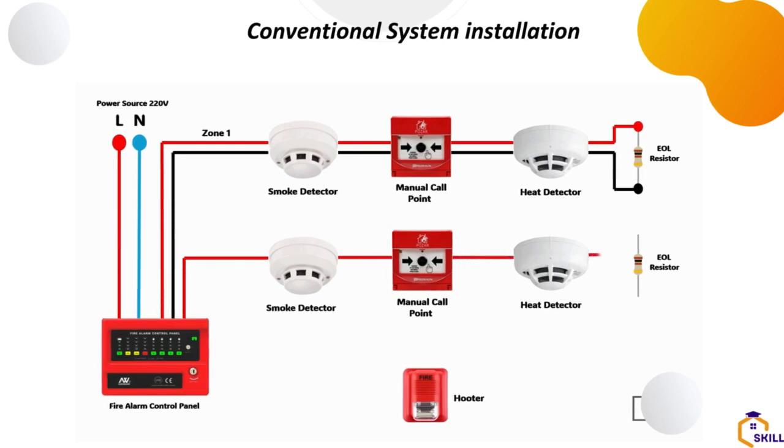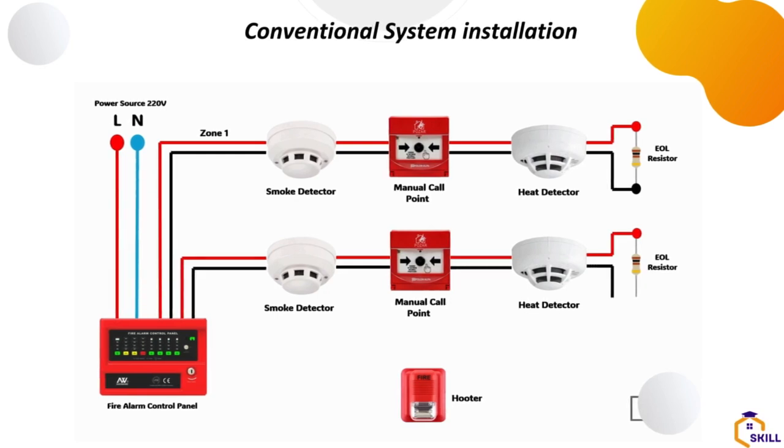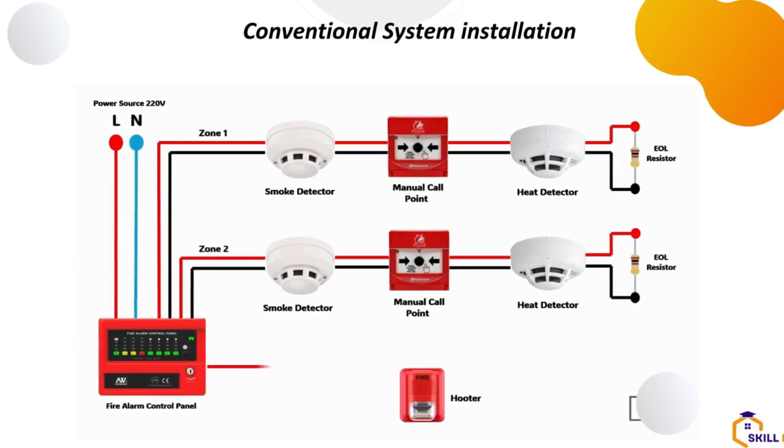This is just basically what you are doing. So the pipe has to link from the smoke detector to the manual call point. There's a link. So when you're running the cable, you drop for the smoke detector, you tie the cable. That's how we usually do it. You tie the cable there, you go to the next point, you tie it, you go to the next one, you tie it, till you get to the last point and get your system ready for mounting of devices.